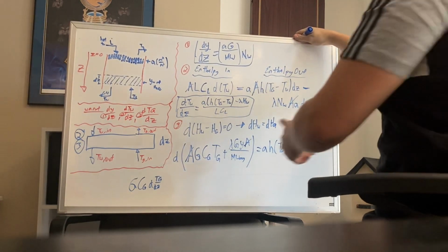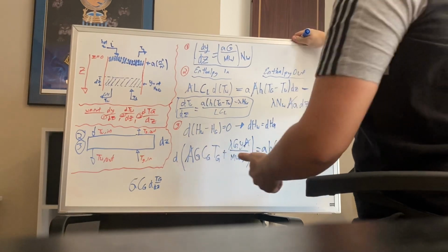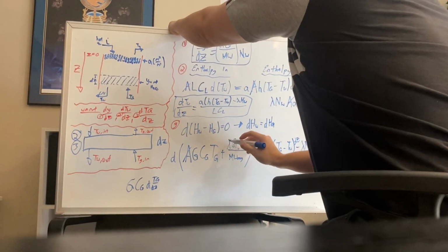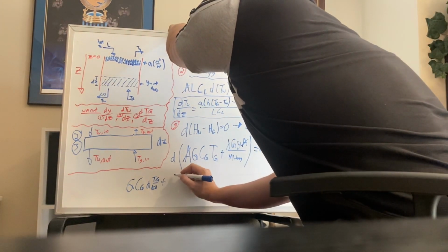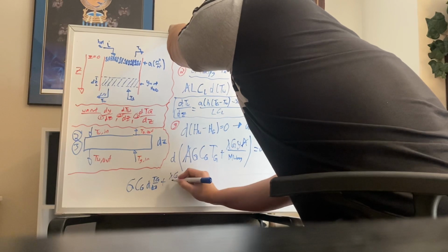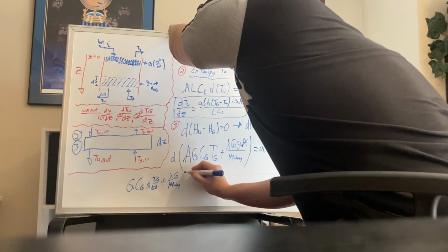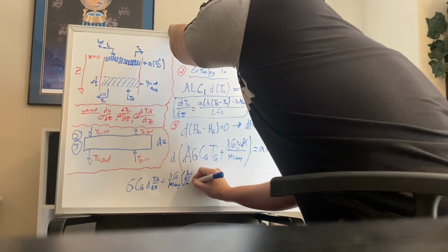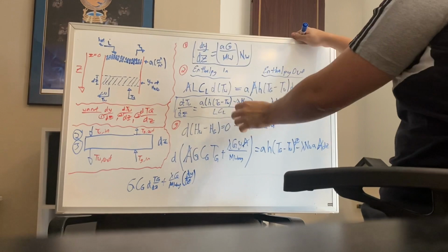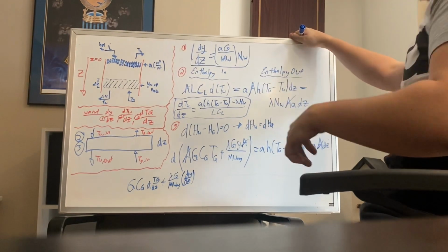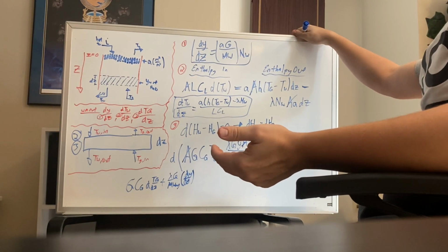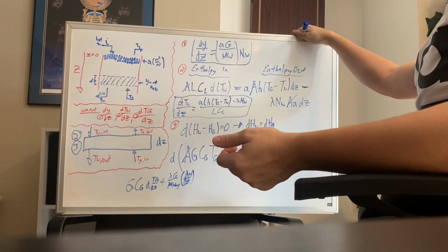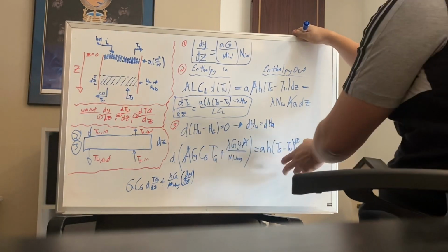And so pretty much doing the same thing over here, we can take out the heat of vaporization, the gas flow rate, and the molecular weight average. So lambda, that, and the molecular weight average. And this is actually going to leave us with another differential, but we solved this earlier, which is dy dz, which we're going to end up having to substitute in to give us our final equation that we're going to be using. But before we actually do that, we still need to equate over this right side